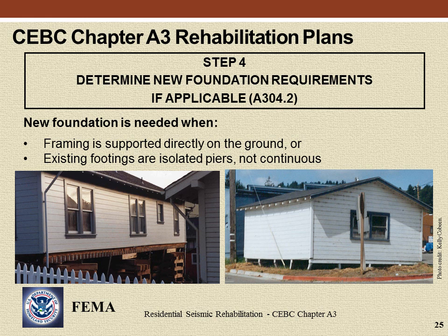Step 4. Determine when new foundations are required. These photos show dwellings damaged by the 1992 Cape Mendocino earthquake. The dwellings have isolated foundations at each wood post. A new continuous foundation or partial foundation would be required for these dwellings.